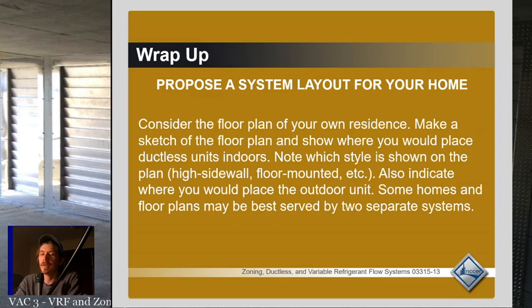So anyway, in general, I say never undersize, always oversize, because sometimes we overstate these humidity issues, but you definitely don't want to put in a 2-ton system where a half-ton or a 1-ton would have been fine, right? Oversizing it by that gross of an amount is a bad idea, except when you're doing all ductless mini splits and they also provide heat. You don't have any option but to oversize in those cases, but you want to do the best you can to keep it as small as possible still, and obviously recommend they run it in dry mode more often, or maybe even do a separate fresh air dehumidification system to overcome the humidity issues.